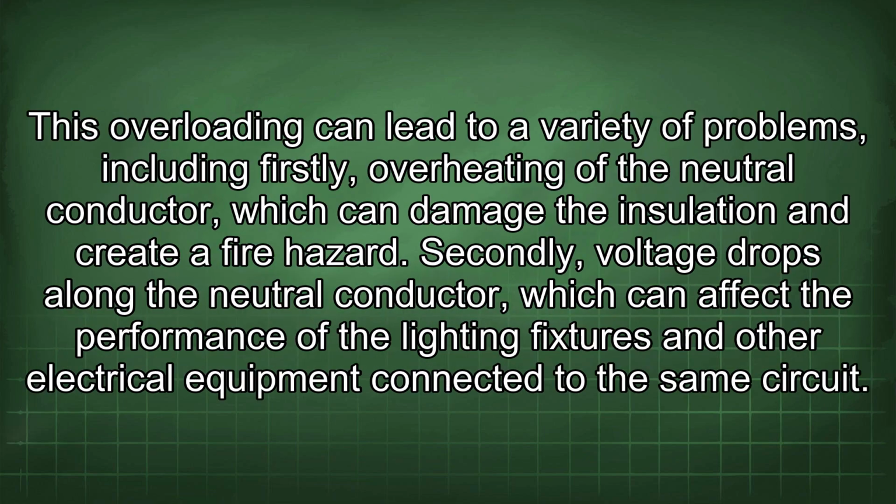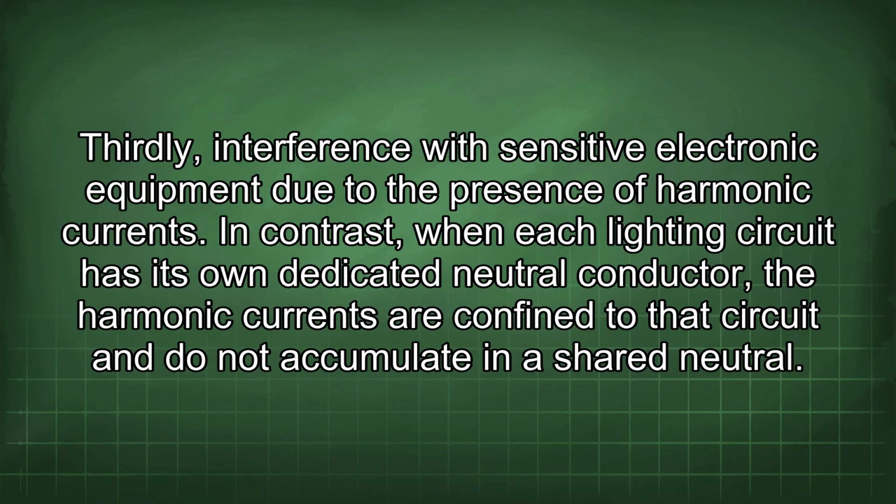This overloading can lead to a variety of problems, including firstly, overheating of the neutral conductor, which can damage the insulation and create a fire hazard. Secondly, voltage drops along the neutral conductor, which can affect the performance of the lighting fixtures and other electrical equipment connected to the same circuit. Thirdly, interference with sensitive electronic equipment due to the presence of harmonic currents.